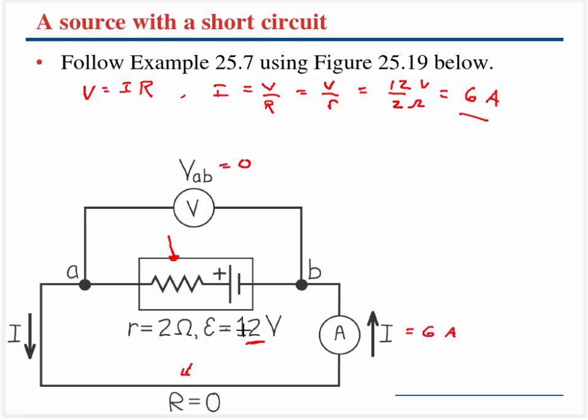One thing to be very careful of when you're hooking up batteries and such is that very typically this resistance is a very small number. So if you hook up a circuit and it has no load to carry down there, then you can get obscenely large currents flowing through that, greatly exceeding the current limitations on wires, and so wires will tend to melt.